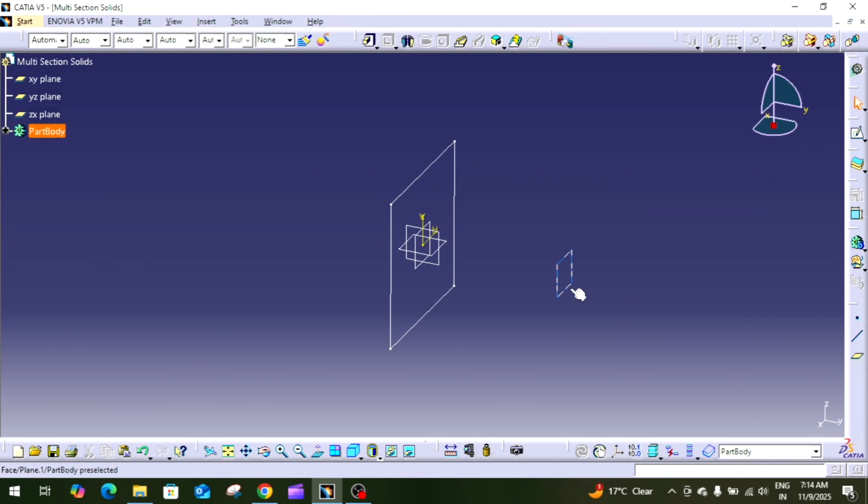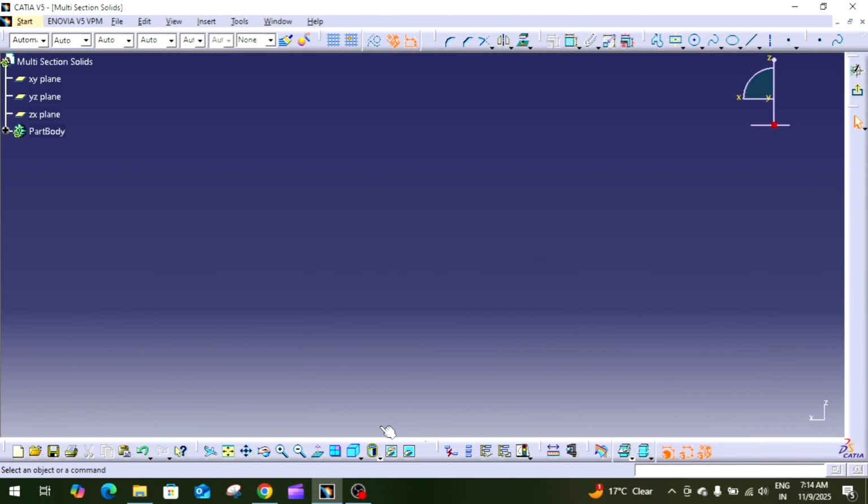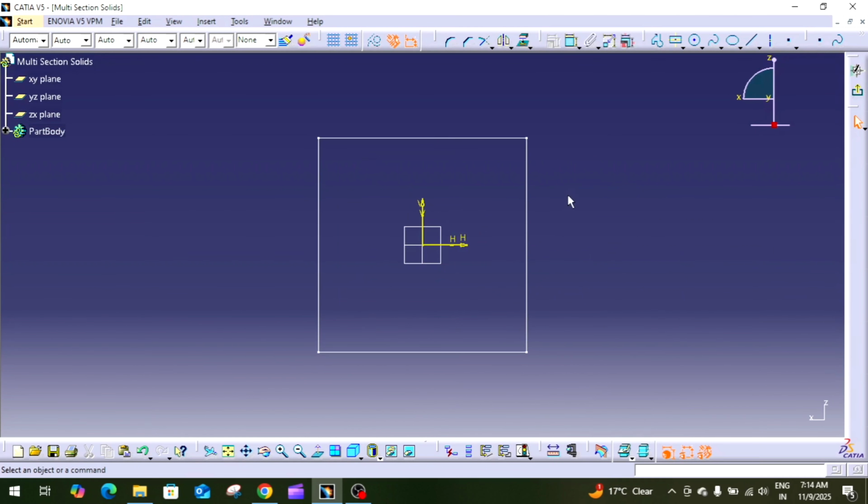Here in this plane we are going to create another sketch. Click on the newly created plane and click on the Sketch tool. The Fit All in option will help you fit your geometry, sketch or 3D model into your working space. Now create another centered rectangle.